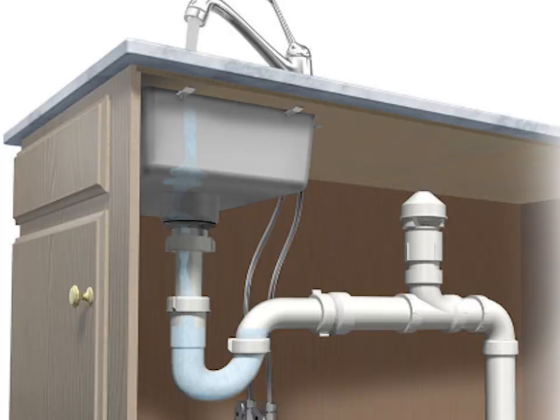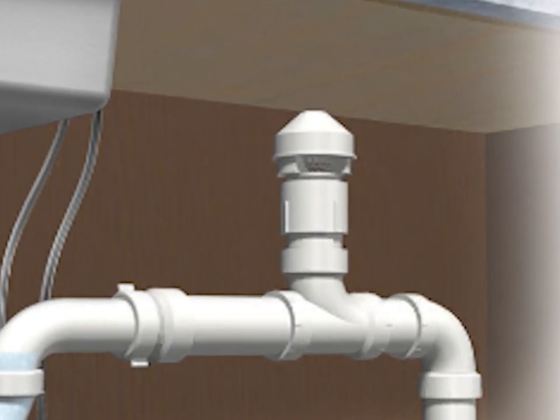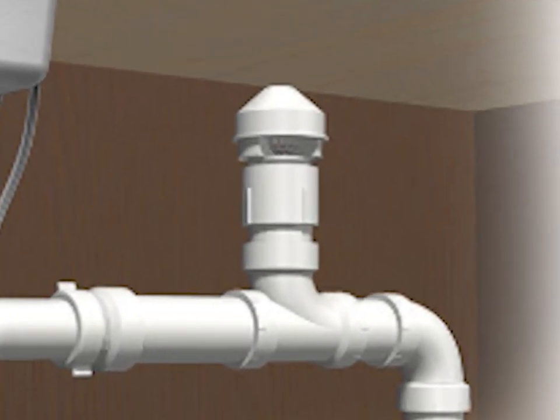The wrong way. Historically, folks would use an air admittance valve, a Studor vent. They were introduced in 1986. They only handle negative pressure, not positive. Preferably, they would only be used in island kitchen sinks where a normal vent pipe is impractical. If legal to be used, they must be serviceable. They can't be in a wall. They must be visible. They are available in most hardware stores, but are prohibited in Uniform Plumbing Code. If your state uses UPC, you need to vent your island through the roof.